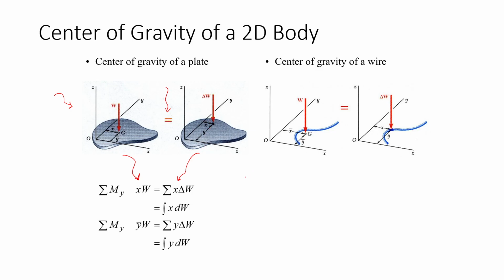So in the area concept, for example, you're going to have an irregular shape figure, let's say this L-shaped figure. For you to better understand the formula, for example, the centroid is at this location, let's say bar x, bar y, and this is the total area.